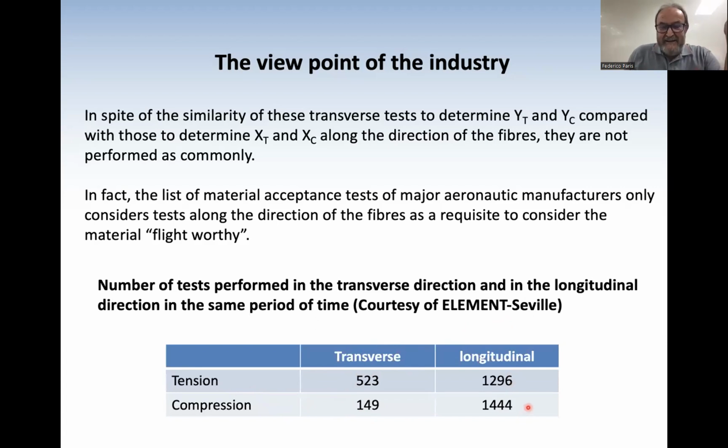Particularly, it is very significant, the difference in compression between transverse and longitudinal, which is 10 times more longitudinal than transverse, which may imply that the industry gets more information to design a component from longitudinal than from transverse strength.